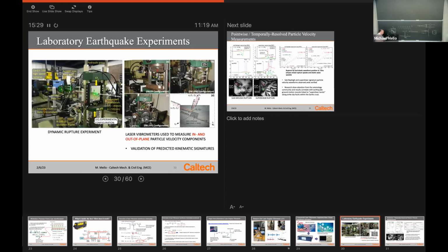So I can't draw U3 on this diagram, but I'm going to show you, suppose we could somehow reflect right off the corner of this tape and get light to come back that way. Literally, we're almost grazing the plate, okay? So these beams are drawn showing you that we're almost grazing the plate, but we can't graze it. That's not possible, right? There's stuff in the way. We're coming in at a very shallow angle, and there's the vibrometer probe right here, sending the light out. It's going to hit the corner of the tape, the retroreflective tape.